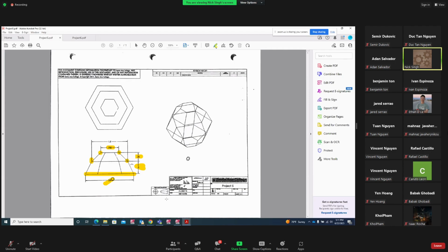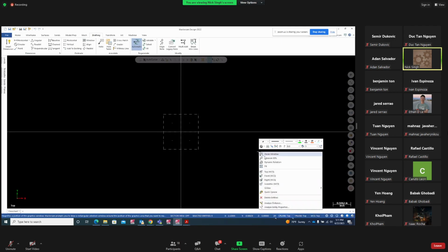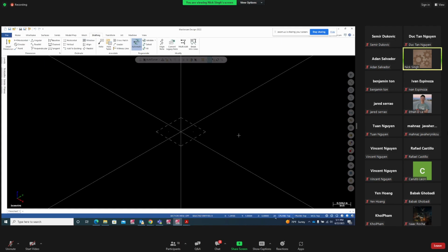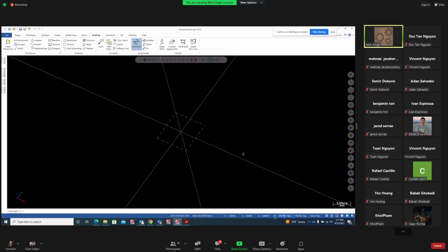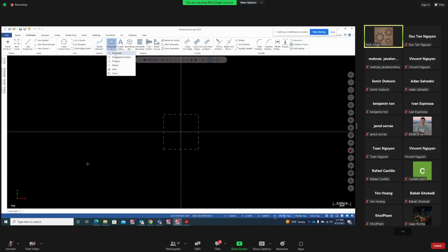All right, so let's go ahead, go to construction plane top and create this first hexagon at Z0, and the distance across corners is 2 inches. All right. So I'm going to go to 2D and I'm going to construction plane top. If you go in isometric and you go to the top plane, that is your construction plane top. And I'm going to go to wireframe, and here in the rectagon, I will have polygon.